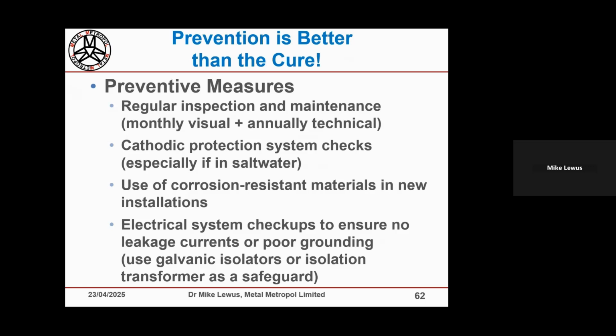One thing I would say is that with pitting, and I'm conscious that when I talk about pitting, I come from, if anything, the stainless steel world, at least in one employment I had. When we talk about pittings, we're often talking about very small pits, not like pits that have resulted from, say, a spalled coating, where you've got maybe a deep depression in the metal that might be about 0.5 centimetre in diameter. Often I've been looking at pits that are very small.